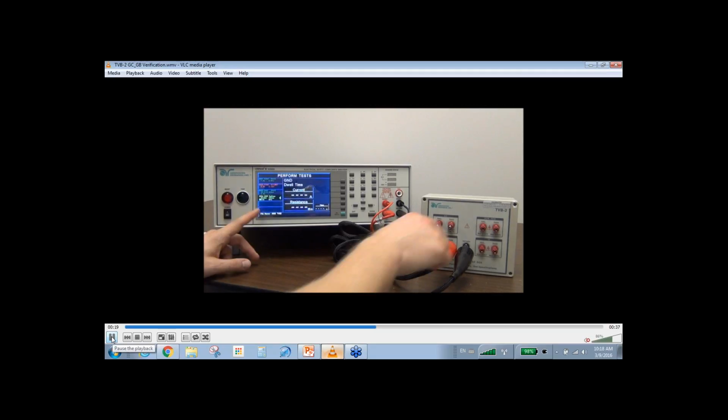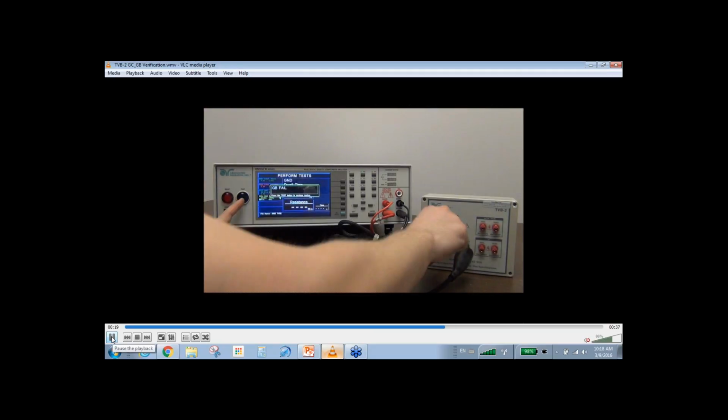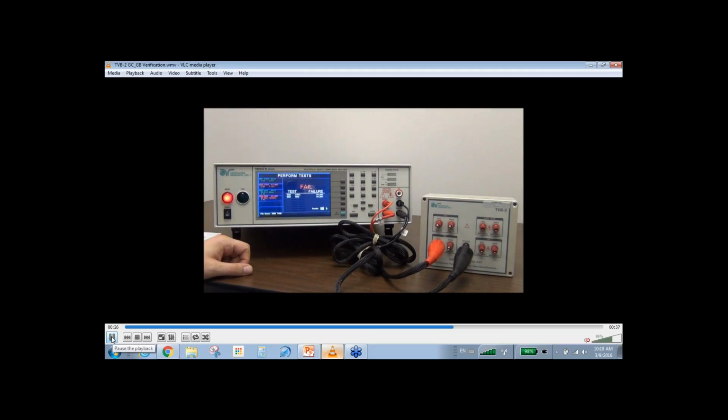Next, we're going to see what a ground bond fail looks like on our testers. When you apply 30 amps of current, this results in the resistance being a lot more than 100 milliohms. Let's take a look at it real quick. On a fail condition, the resistance read between these 2 points was more than 200 milliohms.